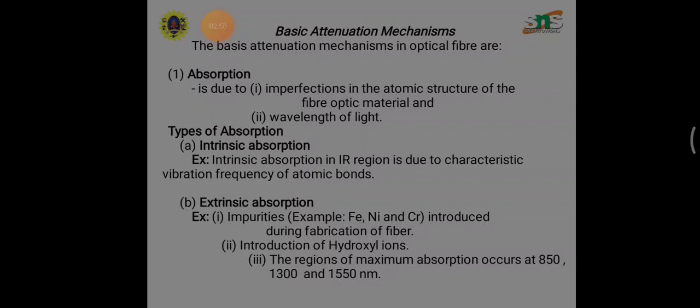So alternative fluoride glasses such as ZBLAN and AlF3 are used in manufacturing mid-IR optical fiber, primarily because they exhibit lower loss at longer wavelengths. Contaminants in the fiber, like water molecules, contribute to absorption loss.